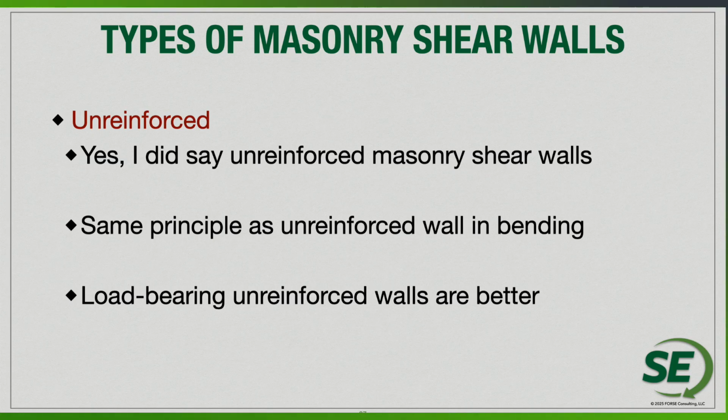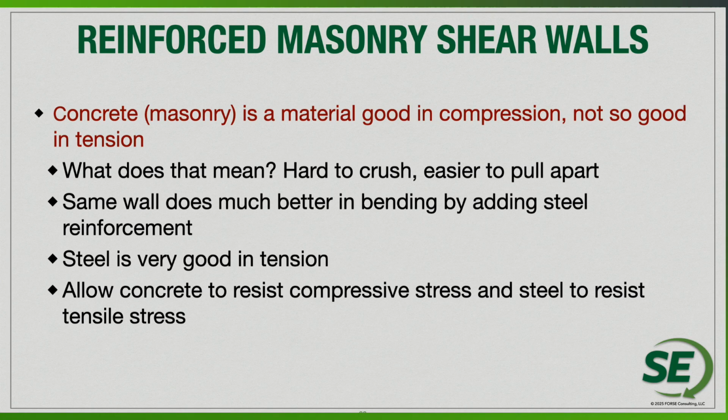So yes, you can certainly do unreinforced. Again, if we have enough axial force, that can certainly benefit. Masonry is good at compression. We've said that before. Steel does add quite a bit more tensile capacity, so it definitely increases the overall capacity very quickly.